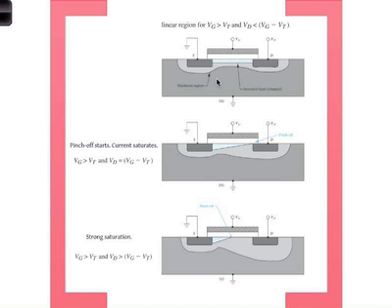Yeah, but like in the p-type material, yes? You wouldn't need any donor atoms. Well, p-type material means you already, that's correct. You don't need donor atoms, that's correct. But you have acceptor atoms, that's correct. Yeah, you don't, because in any material you have electrons and holes all the time, right? The p-type just means you have increased the holes more than compared to the electrons, but you still have some electrons. And what happens here is that you collect all the electrons in the bulk to come to the interface. So locally you have made it n-type.